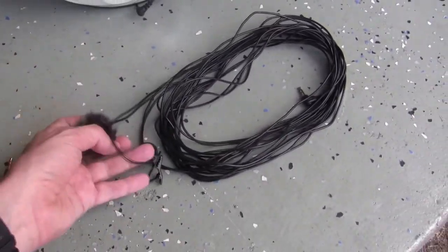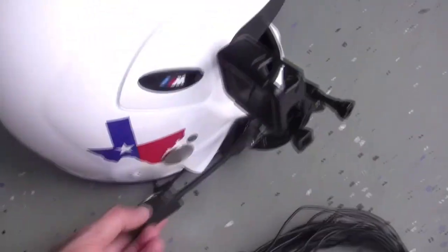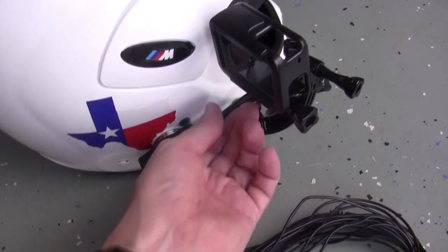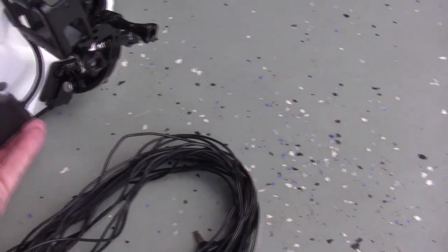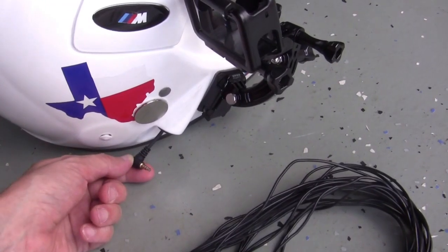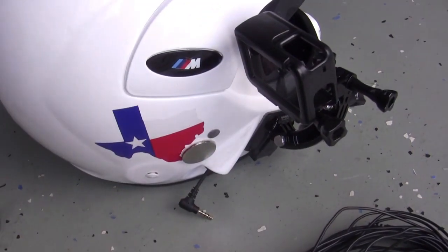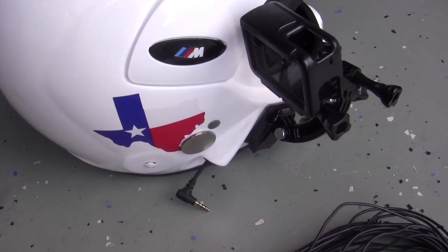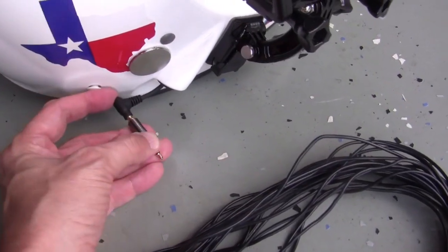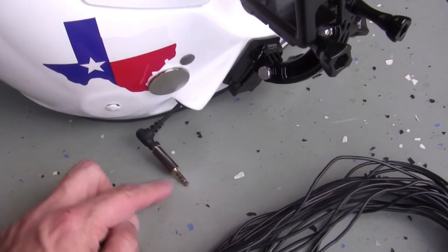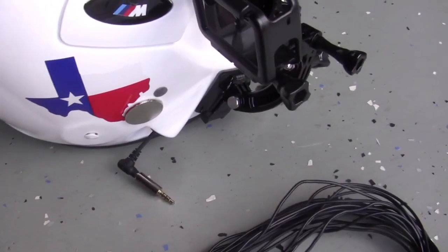Typically I use this long one that I put on my bumper and connect directly to the microphone adapter that sticks on my helmet with a magnet and then plugs into the other GoPro here. And then I also have a headset in the helmet, which is actually using an OMTP standard, whereas everything in the US is typically CTIA. So there is an adapter that converts the OMTP into CTIA. It basically switches the top two connectors. One of them is mic, the other one is ground, and they are different.